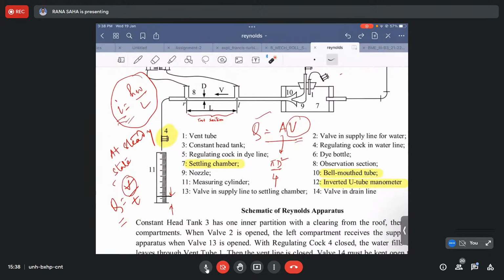And also, it is more important to maintain the synchronization. I mean, the moment you stop the watch, simultaneously the measuring cylinder should be completely released from the water supply. Okay, which means you need to take it out immediately when you stop the time recording.